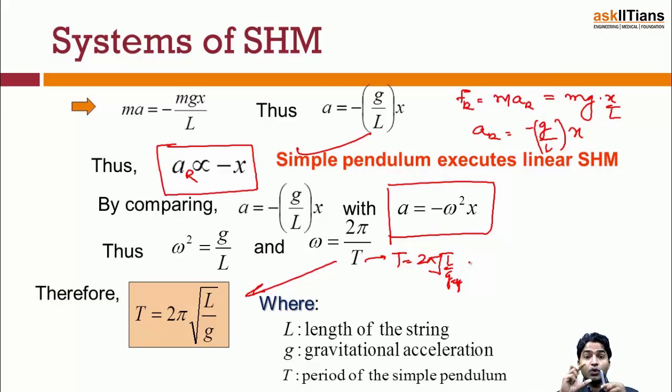Now we will calculate torque about the mean position. So 2kx into L by 2 should be equal to I into alpha. In this way we will calculate our time period. Third case, if there is a ring or a sphere, and a spring is connected at top. So what happens if you give a small jerk? Rotation takes place.